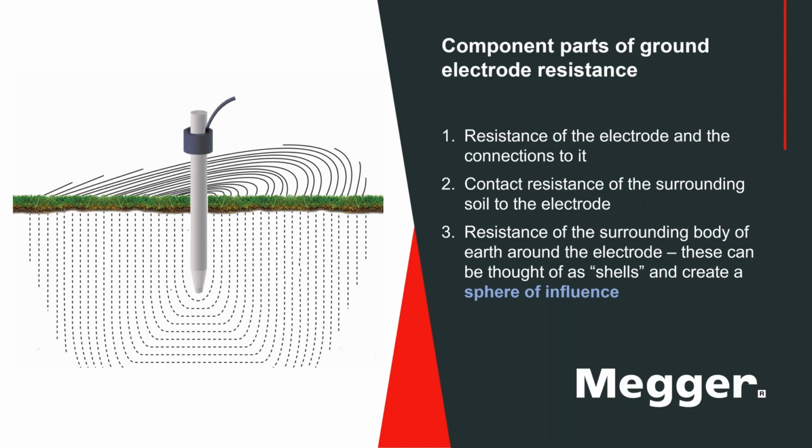So as you encounter more of the soil as you get further and further away, the additional resistance is becoming less and less. And at some point, there is so much volume of soil that there's no additional resistance exerted. That's the point that you're looking for. You want that to be a relatively low number. And so as we test for the grounding resistance of your electrode system, we'll see how we determine that and how it's applied. Next.